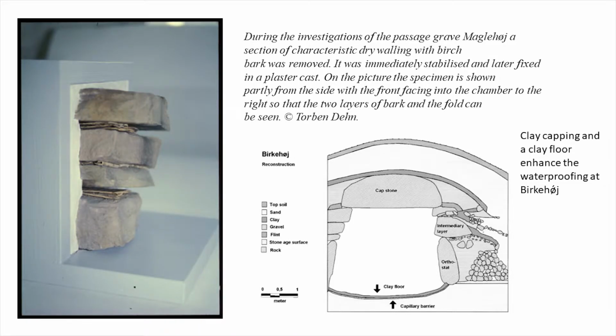Those panels of pinnings can exist from ground level to the top of the gap between adjacent stones, either as a continuous gap or as two gaps, a bottom one and a top one. The pinnings in those gaps have between each pair of stones pads of birch bark, which have been soaked in tree resin.